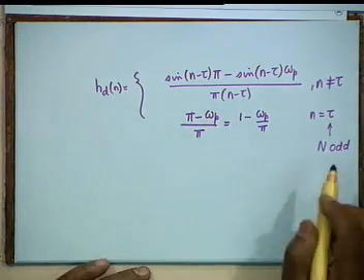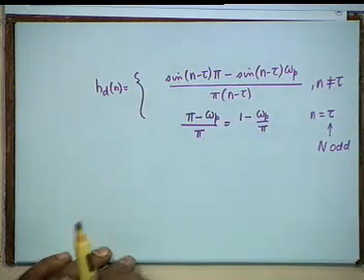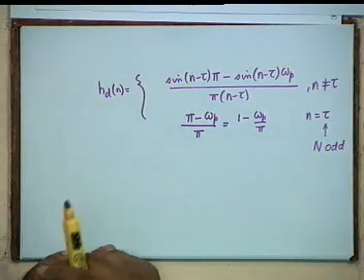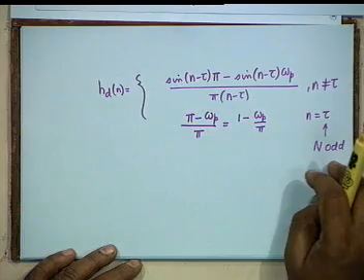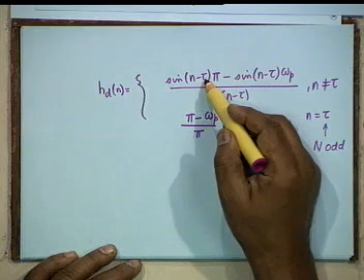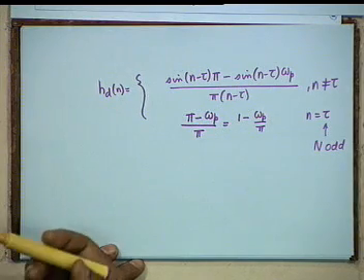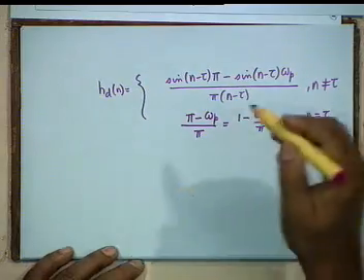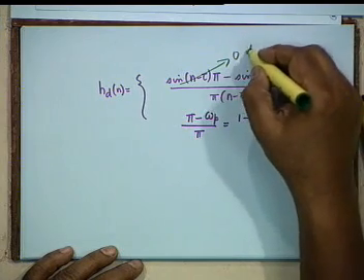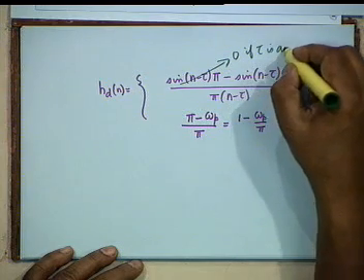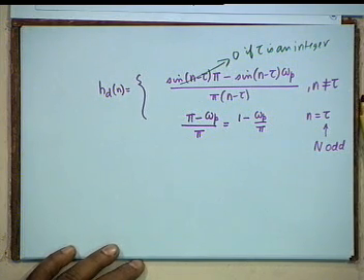All right. You also notice that if capital N is odd, then the first term here is identically equal to 0. This is not the case if capital N is even. Agreed? You see, whatever n is, if tau is an integer, then sine of an integral multiple of pi is always 0. Sine 0 is 0, sine pi is 0, sine 2 pi is 0. Therefore, we make a special notice that this will be 0 if tau is an integer. This is another reason why capital N, an odd length, is preferred.